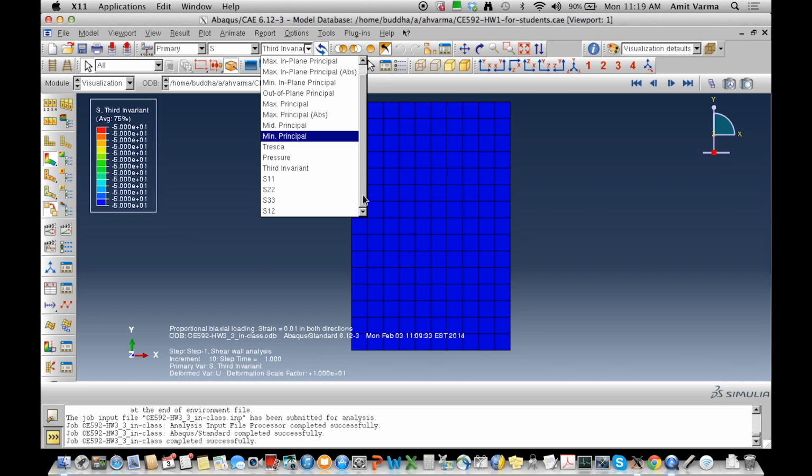So I really need a better example in order to investigate how the yield stresses are supposed to move on this path. Right? That was the first condition. The yield criterion or the consistency condition requires that the yielding point will always move on the von Mises ellipse, and that the flow rule says that it will always be perpendicular to the Mises ellipse.